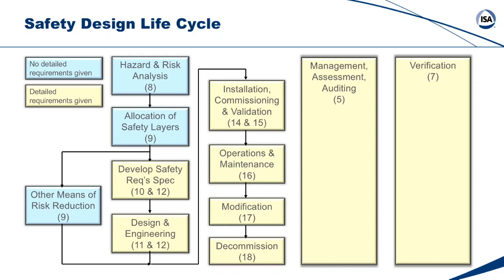So verifying, see the E in verify and the first letter E in the word each, that each step was done. That's verification. Validation is only done once. That's the check that the installed system actually meets the requirement specification. So the overall life cycle, once again, makes sure nothing falls through the cracks between all the different organizations that are going to be involved in this project over years of time. One of those boxes talks about determining the required safety integrity levels.